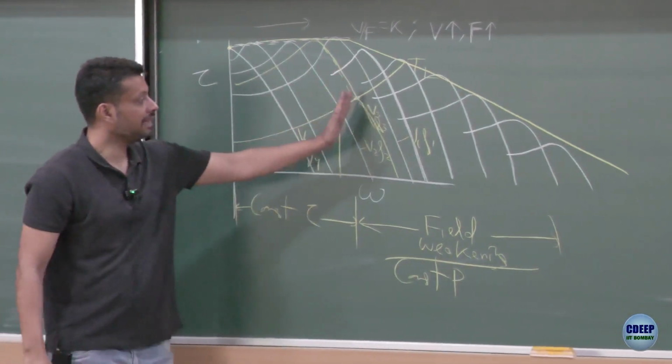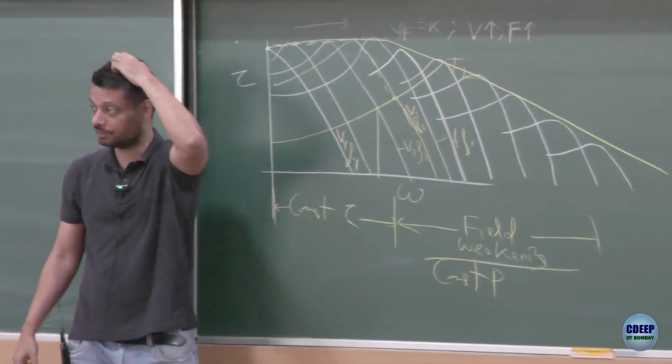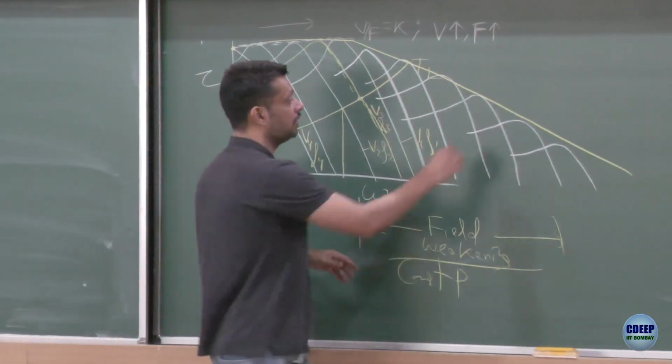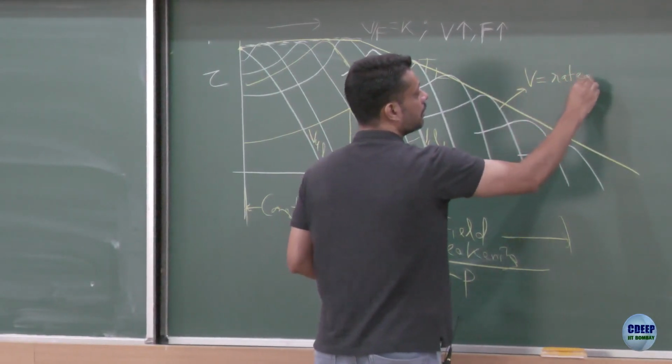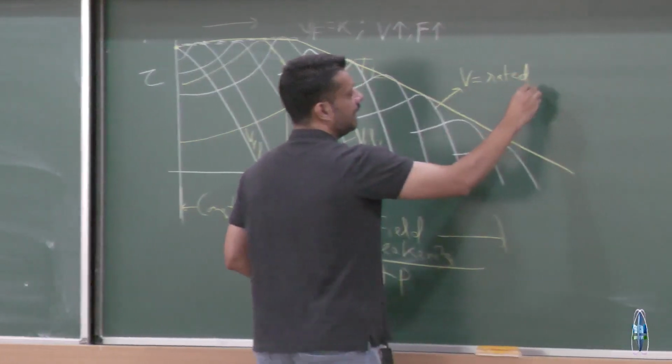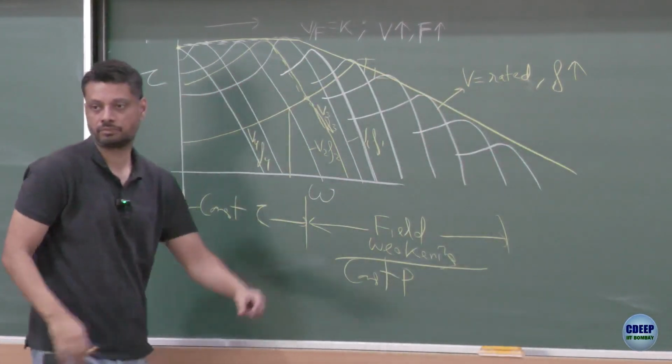So you can even go at much higher speed. Of course your torque capability keeps on reducing, right? Here as you are moving, your voltage is fixed to the rated value and your frequency we are increasing as we are moving from left to right.